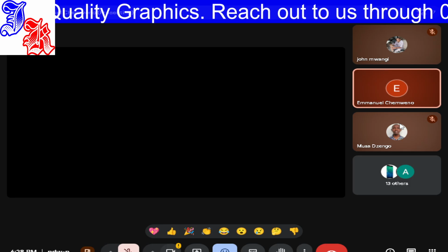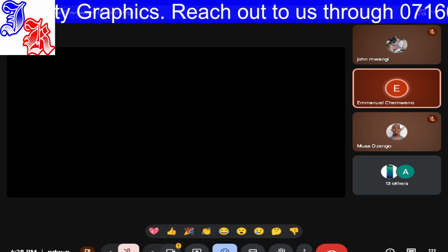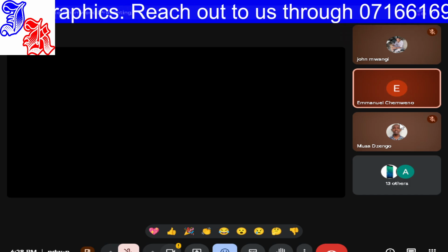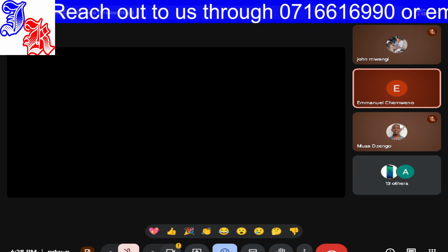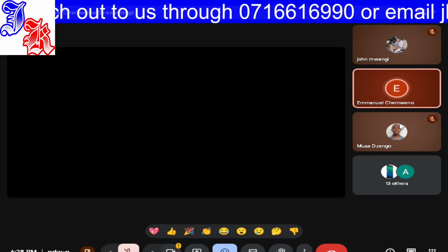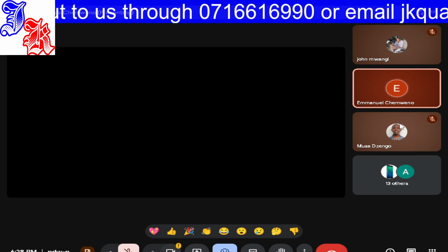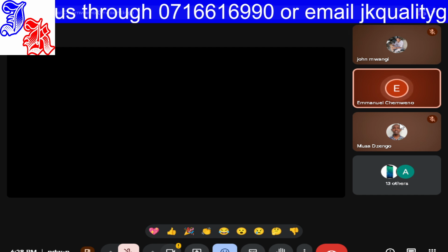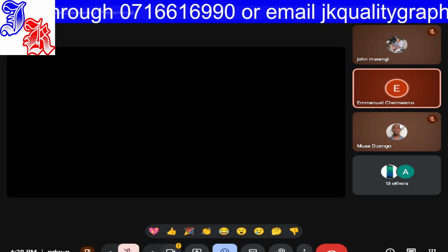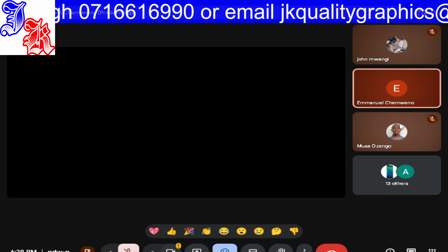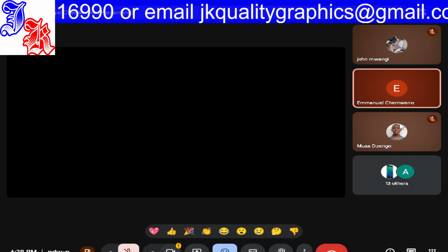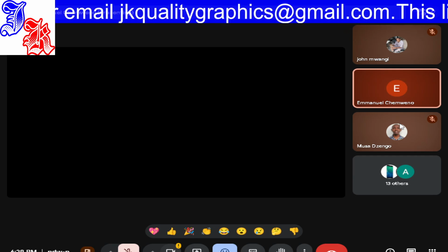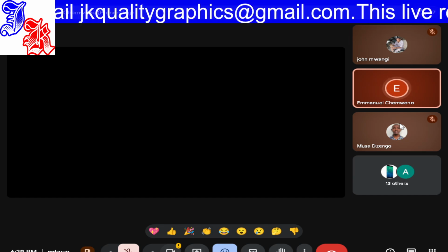Loop 4 is this one, and loop 5 is this one. So loop 4 is this self loop here, and this is loop 5. Loop 5 doesn't share any node, because this is the only node on loop 4, and these are the nodes on loop 5. So loop 4 and loop 5 do not touch. Those are the two non-touching loops.